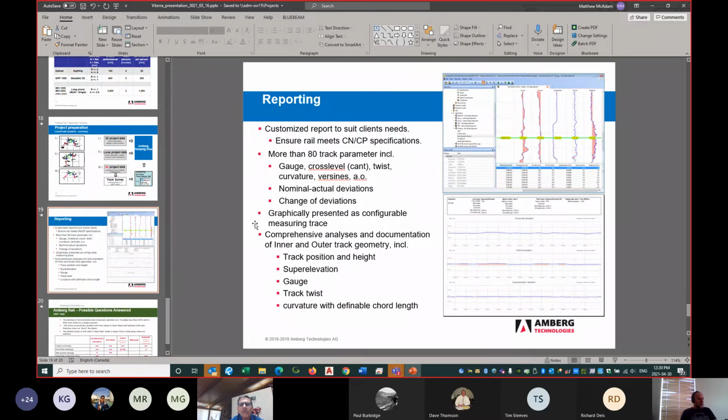So typically what you're going to see, there's a lot of different ways we can do this. And this is something that we're still playing around with, the reporting of it. So typically what you're going to see is you're going to have deviations from your track's parameters. All these deviations are going to be presented in what I like to call a change time series. So what you'll see is plus or minus millimeters along some mean value as you're going along. And that gives you a means of identifying locations that are outside of what your acceptance criteria would be.